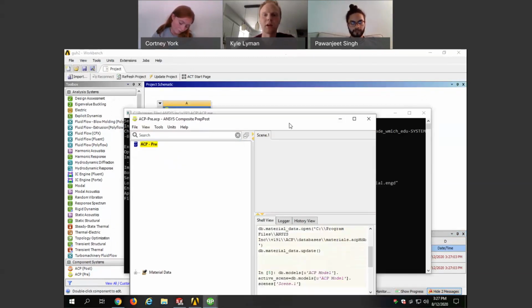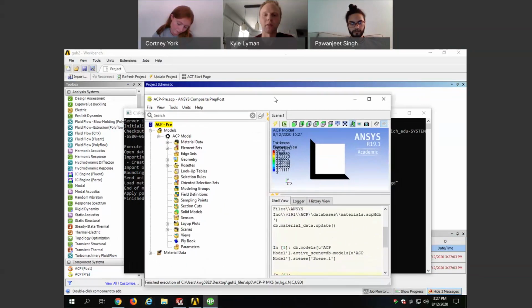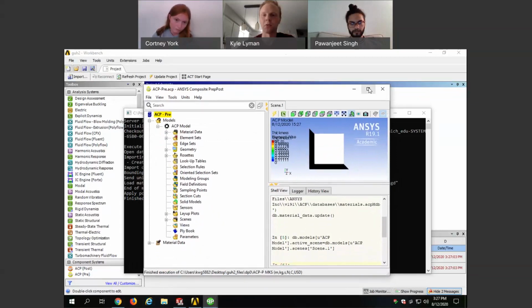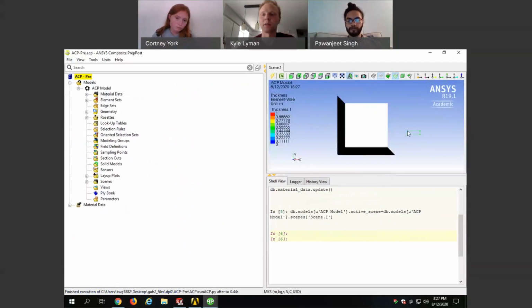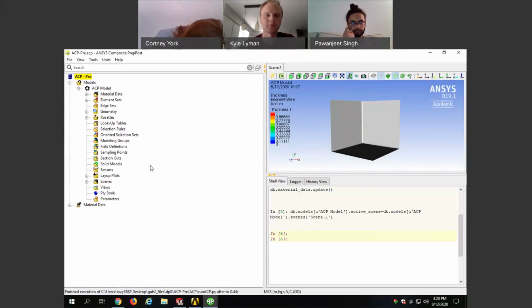And it's here. Now this is kind of the meat and potatoes of the program, ACP, which means that now we're really truly getting into ACP. We've done all the setup, and now we need to start putting our plies of carbon on. So this is just like any other window you can rotate around. It gives you a dummy thickness here. It doesn't mean anything right now because it has 0 thickness at this point. And here it tells you your units too, which is in. So we're going to go ahead and start adding some thickness.